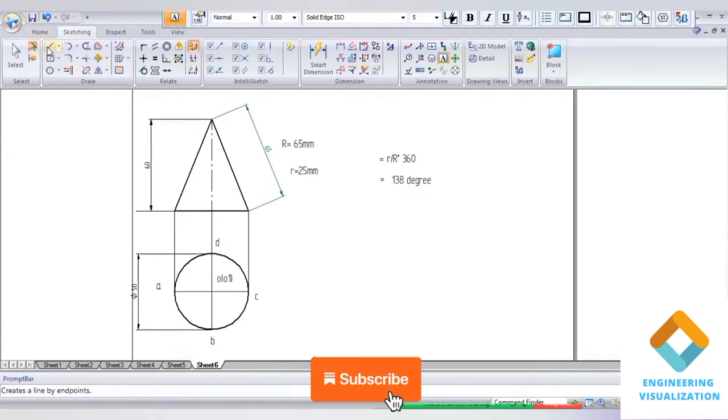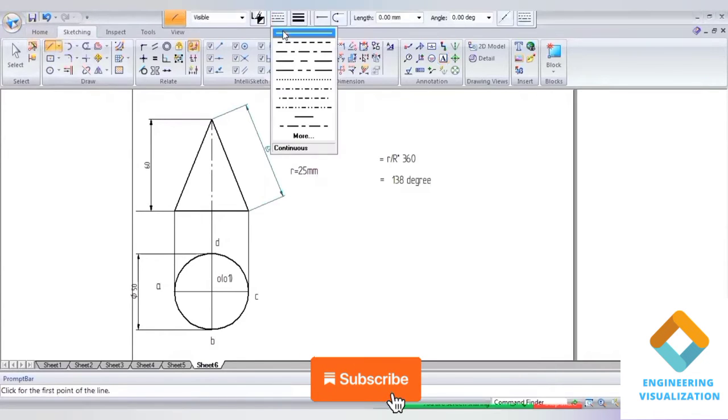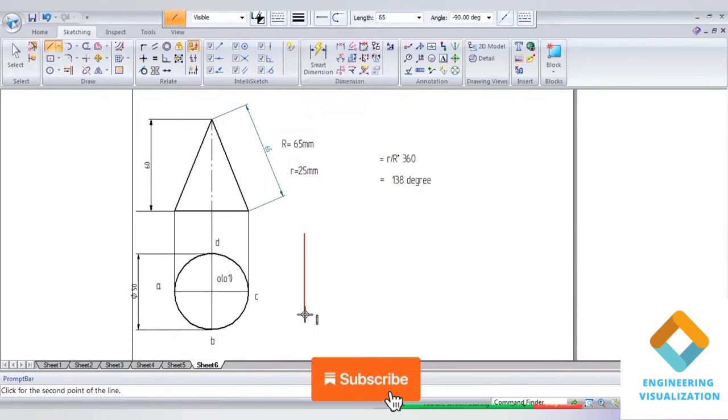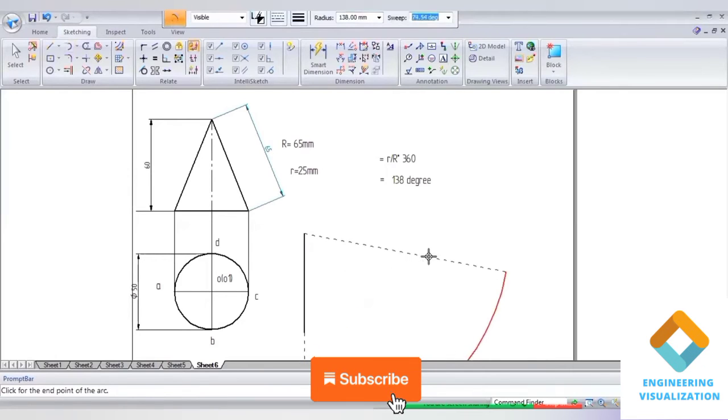First we have to draw one vertical or horizontal line, whichever it is, for a length of 65 mm, that is capital R. We have to draw 65, and then go to arc by center. Select this 65 mm and give the angle, that is 138 degrees.